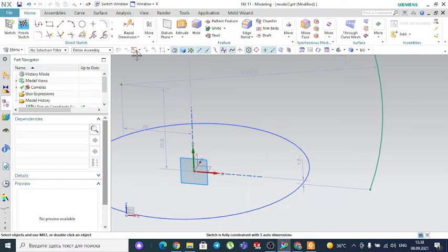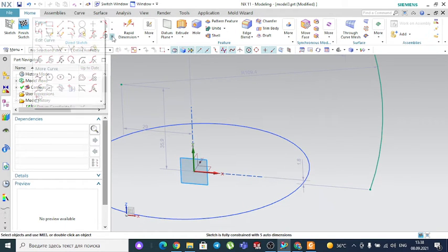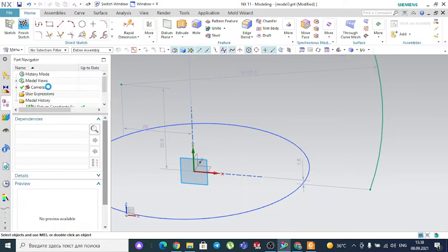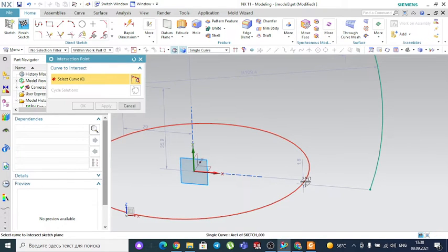In this case, I will use this. So you see this plane is active. If I extend this plane, it intersects directly on this point. So if I use this intersection point function here, you see, it directly creates the point at the intersection of this datum plane. So here the intersection point is activated, and I select this line.